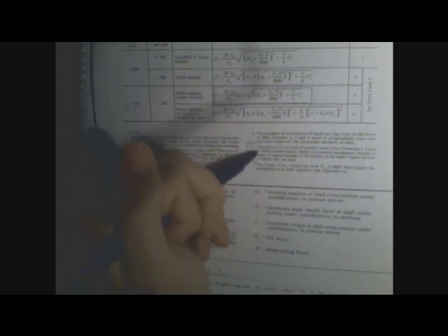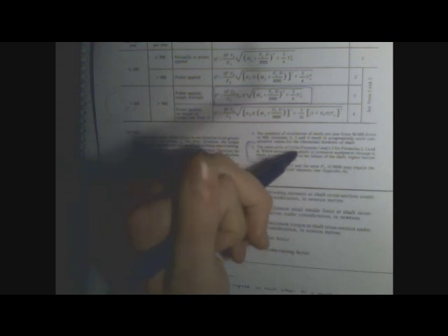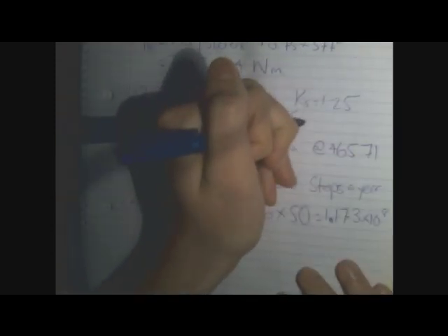And then down here at point number 5 will give me my FS value. The value of FS is 2.0 for Formula 1 and 1.2 for Formulas 2, 3 and 4. So my FS value is 1.2. FS equals 1.2. And that should give me everything I need to calculate my diameter.